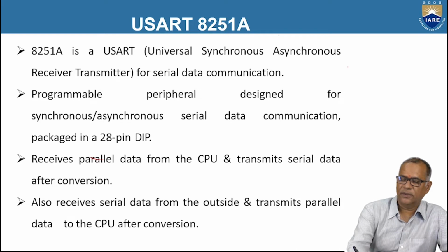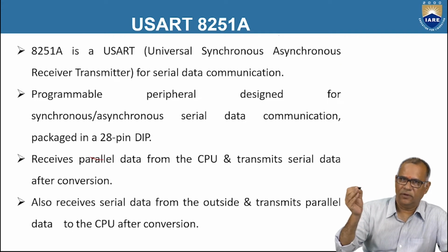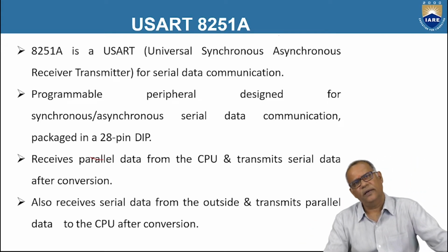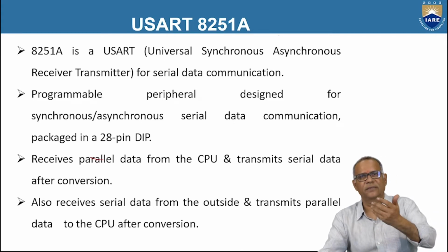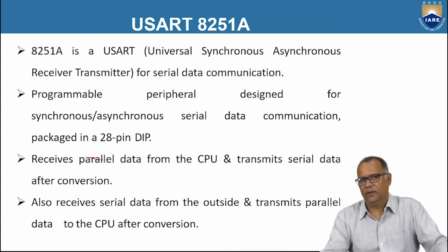So what is asynchronous communication? In asynchronous communication, you have one start bit followed by the data bits, followed by the stop bit, and it may also include parity bits. Whereas in synchronous communication, a group of characters are sent which are separated by the sync pulses.